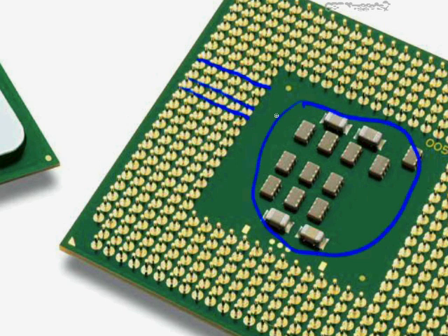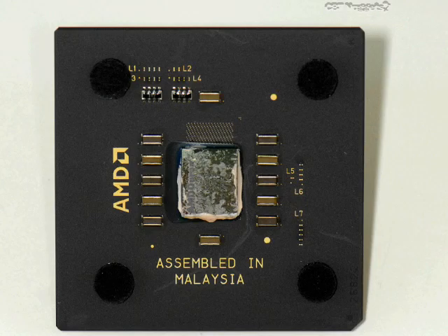where these chips are actually visible. AMD used a similar thing as well, where you can see here that a lot of the chips on the processor are actually visible and actually somewhat vulnerable. Notice that this also has some rubber bumpers on it, and these were designed to help protect the chips from the heatsink, because with the Intel processor I just showed you, and this one as well, a lot of the heat sinks that you push down on, you really have to apply a lot of force. And it sometimes would cause the heatsink to come into contact with these chips and to cause problems or to damage them or to crack something. And by the way, the goo that you see on there, that's just some thermal paste that was put on this particular processor to prepare it for its heatsink.